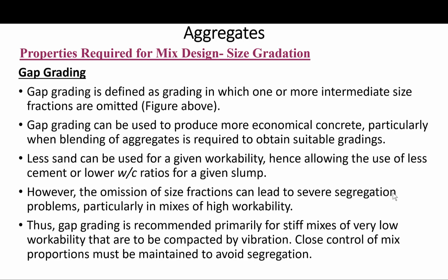On the other hand, ASTM C33 allows the finer fractions to be reduced or omitted if the concrete contains certain workability aids, such as a mineral admixture or an air entraining agent or high cement content. But the ASTM limits the very fine fraction passing the 75 micrometer number 200 mesh sieve to not more than 5% for most concretes, and 3% if the concrete is subject to abrasion.